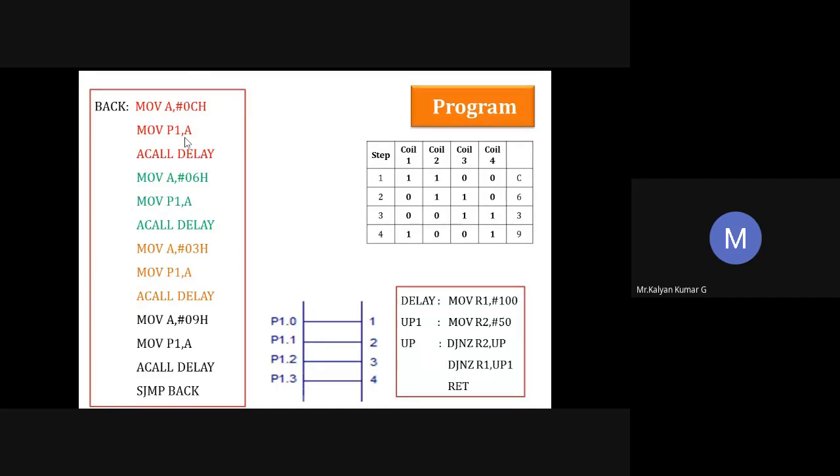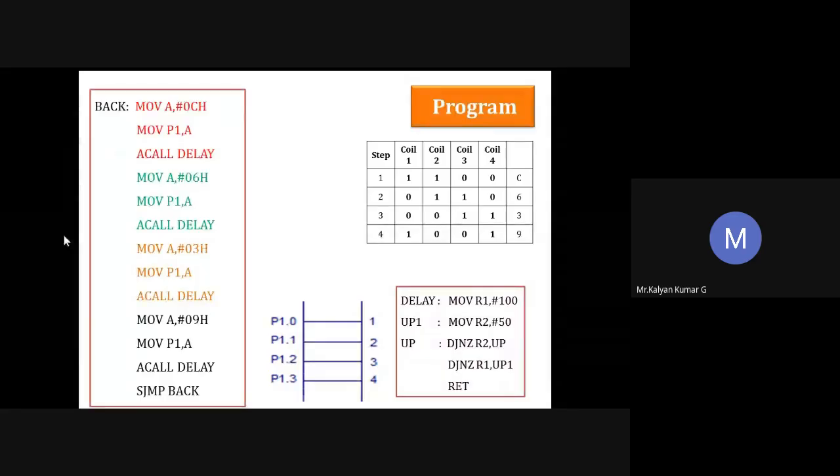We have to wait for the motor to settle in the new position, so that's what this call delays. This is a complete diagram where it shows all. As I said, a delay is required. The delay is necessary to allow your motor transients to settle down or die out. Here is a delay program where I'm initializing some registers to set some time duration.